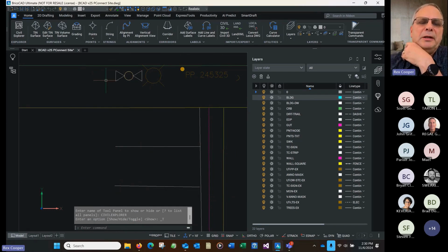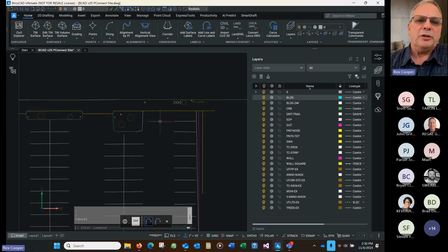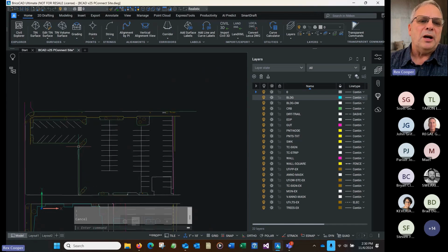And here it put in a fire hydrant symbol, a street light symbol, and a power pole symbol for those. And here, if you notice, this guy wire symbol is rotated back towards the power pole symbol. This power pole had an attribute, and through those codes, you were actually able to tell it, hey, put that value in the attribute value of that block that you're going to insert. And it's just you saying yes or no.